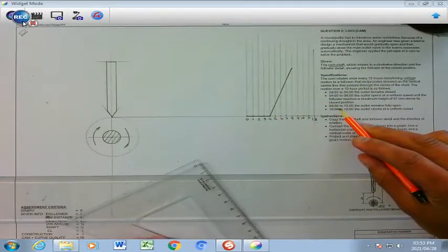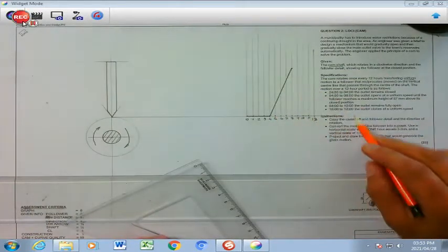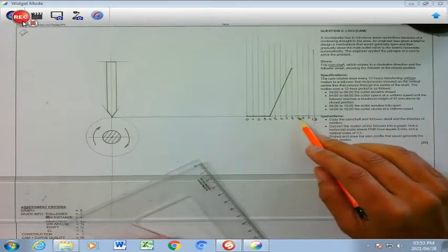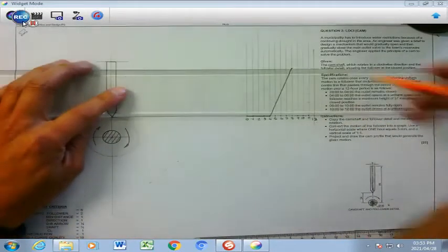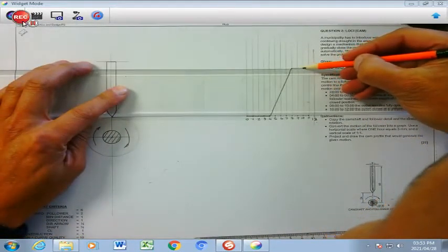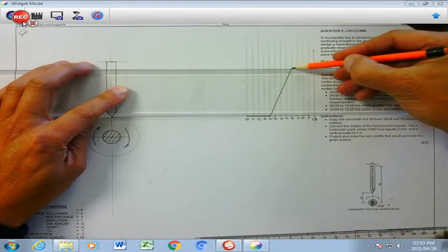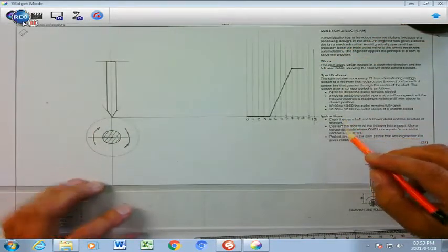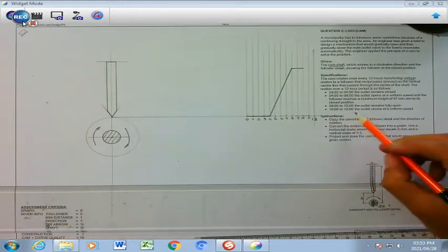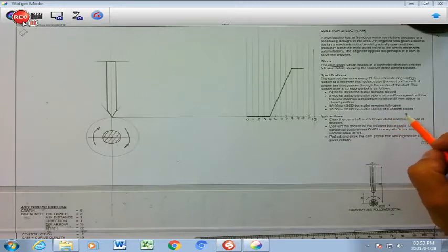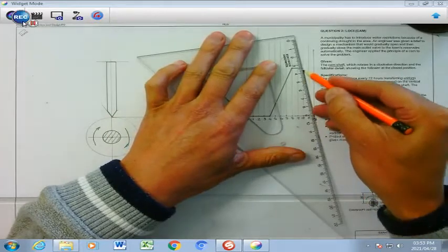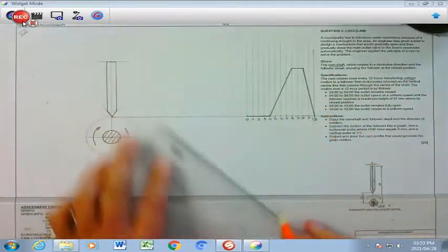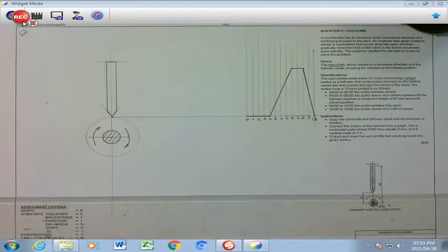It says here that from 8 o'clock, where we are now, to 10 o'clock, which is 2 hours after that, the outlet remains fully open. So open is going to be just going straight like that. There's no movement at all. And then the last bulleted point states from 10 o'clock to 12 o'clock, the outlet closes at a uniform speed. So it comes down right to its origin from there. Okay, and there we have concluded the cam displacement diagram.